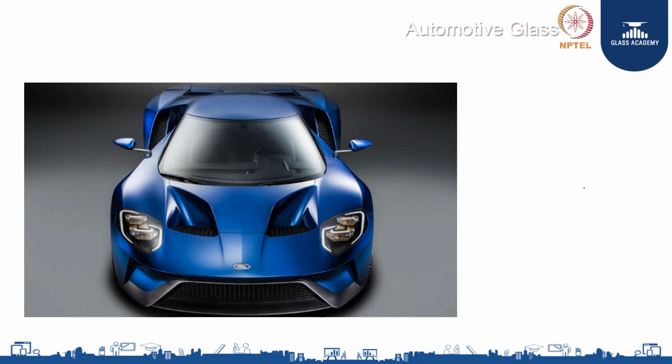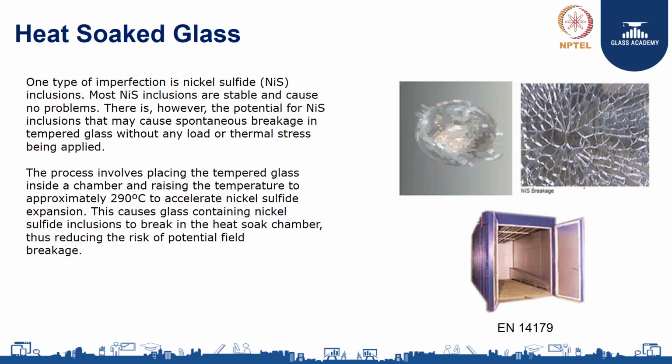In the event of breakage, the glass would not hurt the driver or the occupants inside. The PVB layer protects them: though the glass breaks, any stone or obstacle does not pierce or pass through it. This is the windshield application, which car manufacturers widely use.